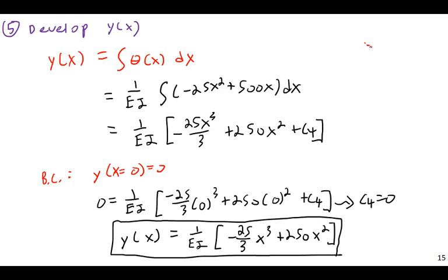And I believe we'll maybe work through some of this in the next class, but the issue here is that if you have a beam that is deflecting like this, then you don't know the slope at either end. So what you would actually do is you would know two other things. You would know that the deflection at this end is 0 and the deflection at this end is 0. So you would run through the whole integration and you'd end up with a y as a function of x with both a C3 and a C4. And you would use those two known positions to find the C3 and the C4. So that's the method for that.